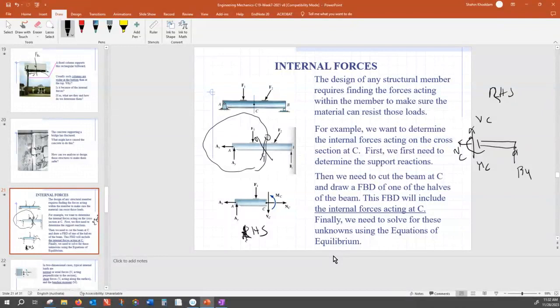That is simply a convention, on the next slide. It's not a big deal, but you have to remember the convention, because otherwise you find yourself confused about the sign. All right? The very same way in a truss structure, we assumed everything was in tension. When we did the method of sections and the method of joints, we assumed everything was under tension. Later on, we could have been proven wrong.